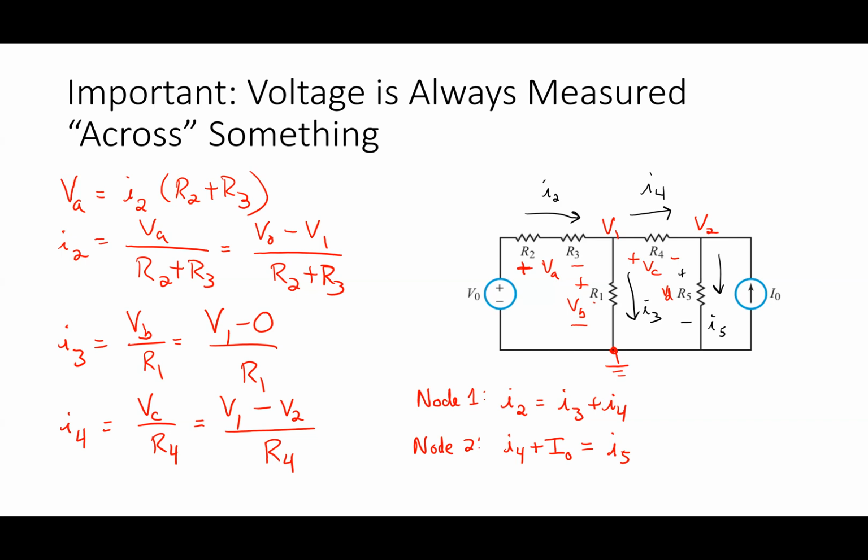Now, why this is important, like on that first exam, you guys gave all kinds of answers. But I look at this, this is a KCL, amps equals amps plus amps. Amps plus amps equals amps. All of those are in terms of amps. If I'm careful about that, how do I know they're in terms of amps? Because they're volts over ohms. But I can track to make sure. When I get super nodes and stuff, I see you guys doing all kinds of stuff where it's like volts minus volts equals amps, right? And so you see all kinds of crazy stuff forming. One thing I like to check is when I look at these things, I can see what the units are.